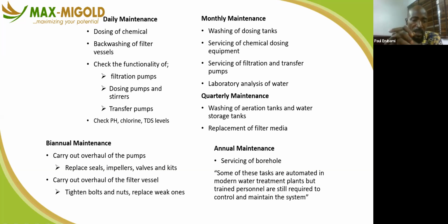Then biannually, carry out an overhaul of the pump, replacing the seal, impeller, valves, and kits. Carry out an overhaul of the filter vessels, tighten bolts and nuts, and replace weak ones. Then annually, you can service your borehole.